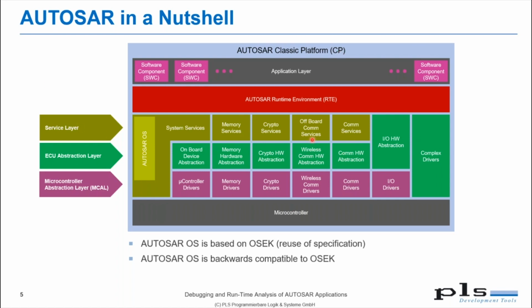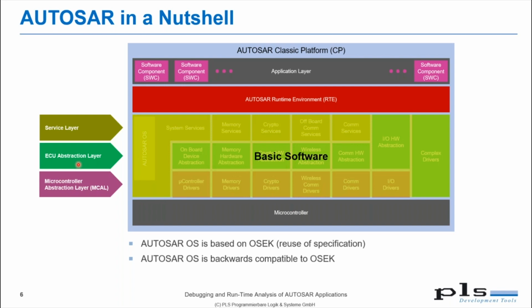When we look at other pictures, then you will find that the layers here are typically summarized as basic software. And on top of the basic software, there is the RTE, the AUTOSAR runtime environment. And this RTE provides the interfaces between the application layer and the basic software here.